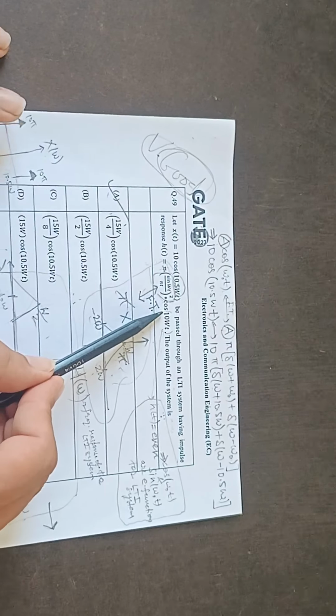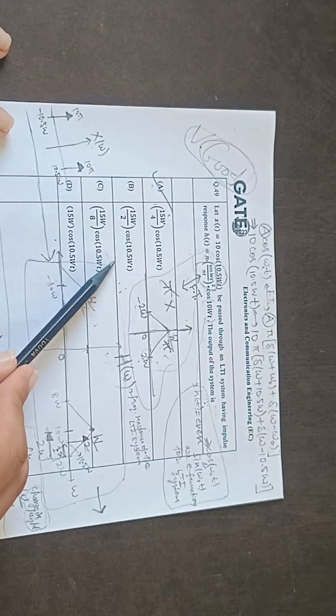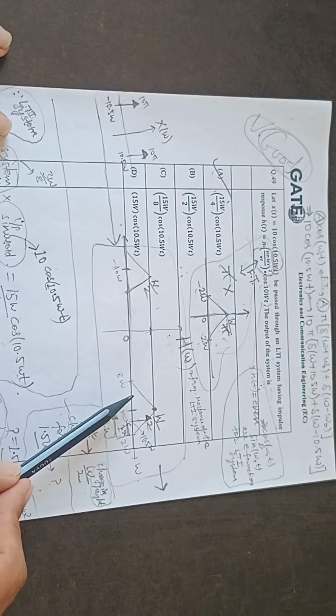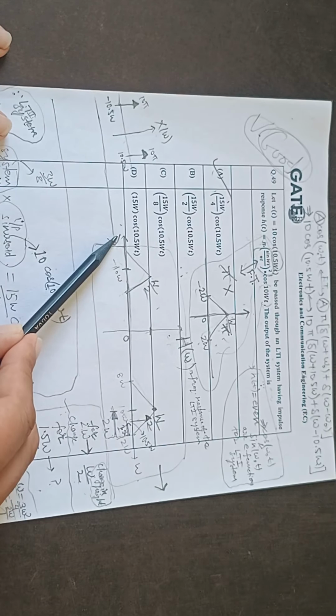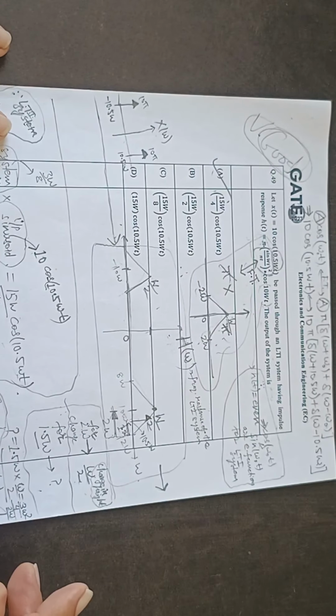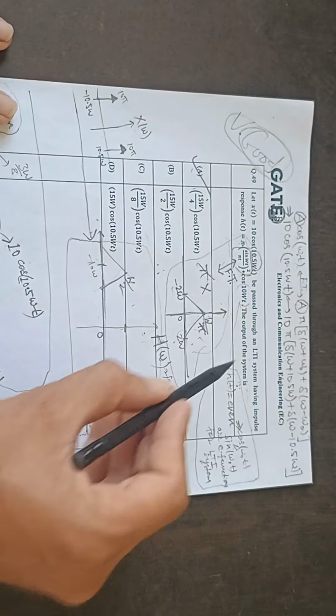Now it is multiplied by cos 10 omega, so by the modulation property this spectrum will shift to 10 omega on both sides. So this will be 12 omega to 8 omega, and then minus 8 omega to minus 12 omega, and the width is w by 2 because the height is halved after modulation. And similarly the input is